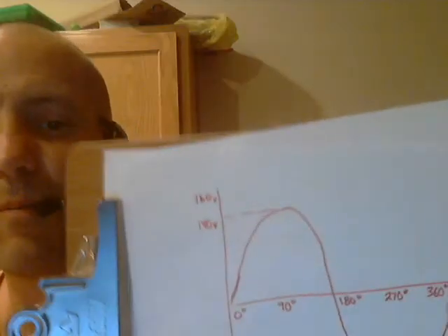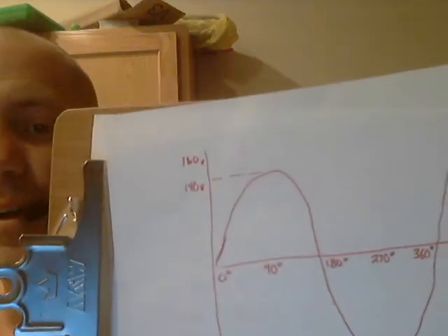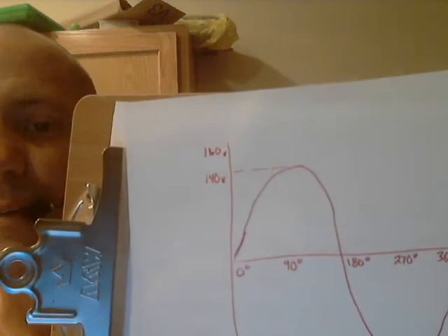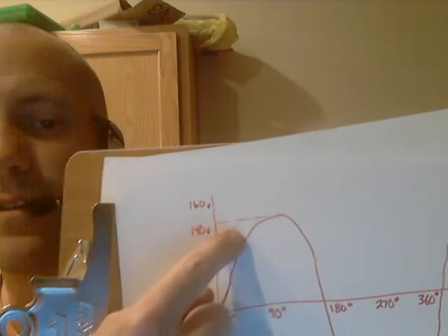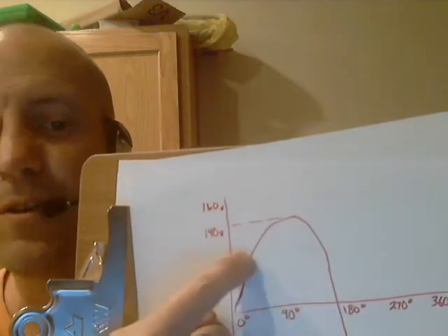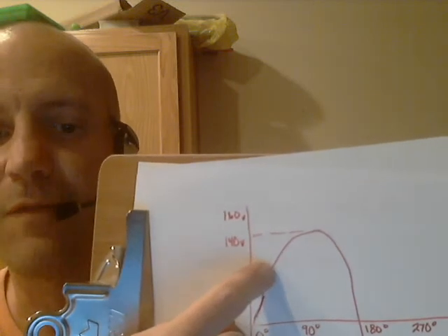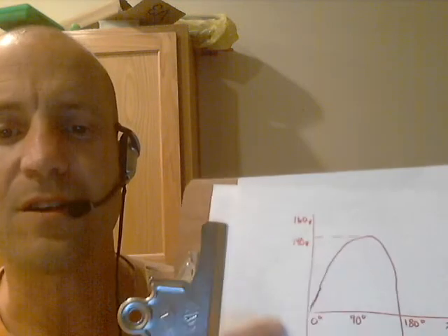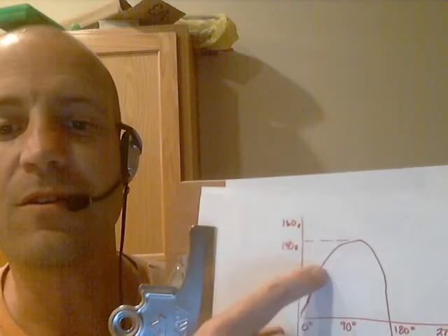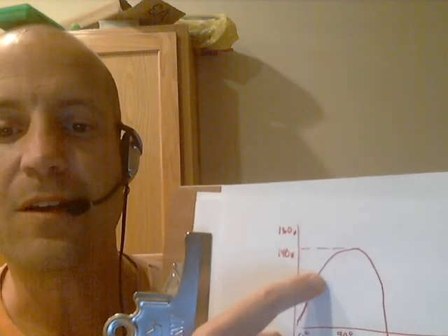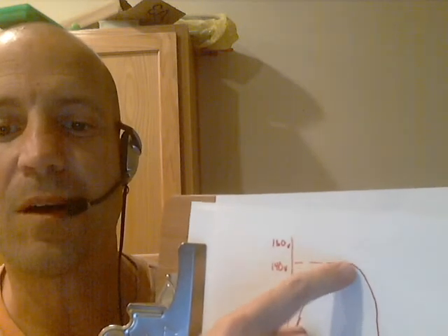because this signal forms what's called a sine wave, we can actually find out what the voltage is at any point along this continuum. So let's say I wanted to know what the voltage was in my generator after 40 degrees of rotation. In other words, it's at the 40-degree mark, right before its first positive maximum, or peak value.